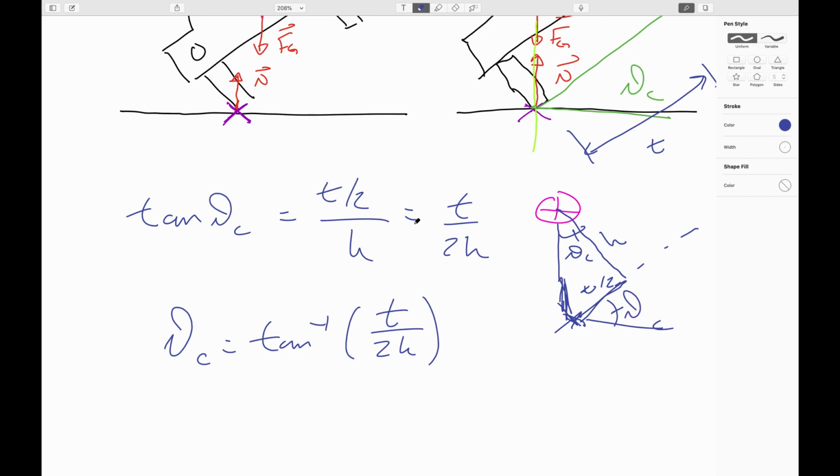This is part of why there's been a lot of work done with pickup trucks, because since pickup trucks naturally sit high, there's been a lot of work done to try to shift components of the vehicle lower, make the wheelbase wider, everything you can to make it harder to flip, just because this height of the center of gravity for a pickup truck is typically higher than for a passenger car. In the other extreme,